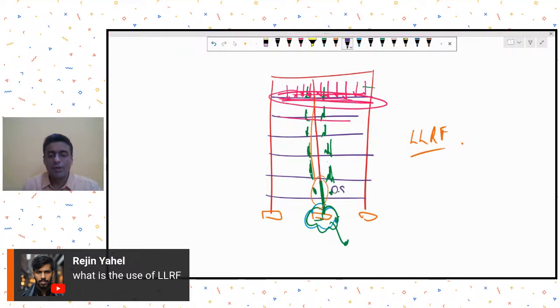So maybe for the ground slab I take only 80% of live load, here I take 70, here I take 60, whatever. These factors are given in IS 875 part 2, that when you want to design these substructures or vertical elements, you could take a part of this live load for your design. So you can go to IS 875 part 2 for an explanation on the live load reduction factor calculation. Okay, very good.